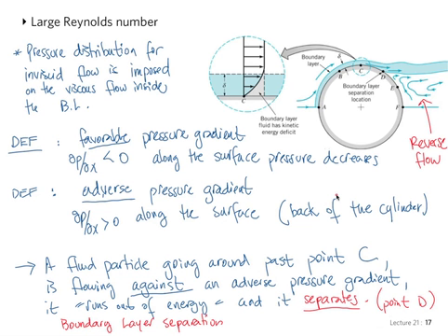And this reverse flow results in an average pressure in the rear of the cylinder, which is much lower than we would anticipate, much lower than in the front half. And this produces an added effect of drag, which we call the pressure drag. And no matter how small the viscosity, pressure drag is always present because of this effect that I just described.